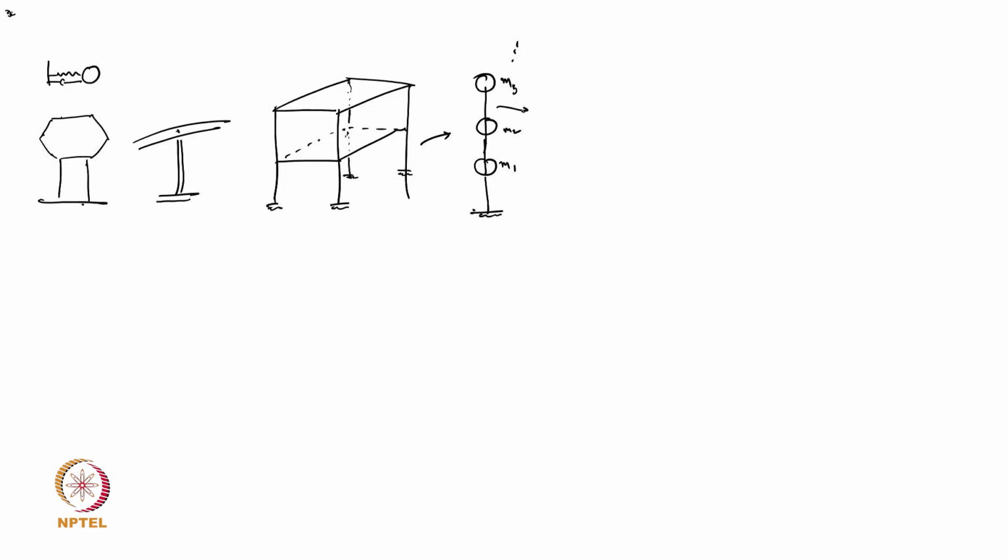And these are the column stiffnesses. However many columns there are, we can accumulate the total stiffness and say that this much stiffness is coming there. So that is K1, maybe from the bottom stilt portion, then K2, K3, and this way the stiffnesses come. So we can see that the structure no longer remains a single degree freedom system.